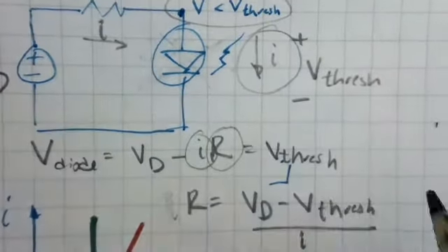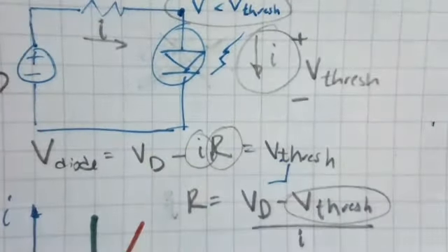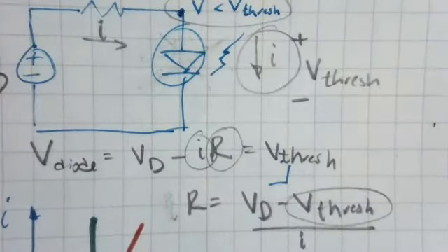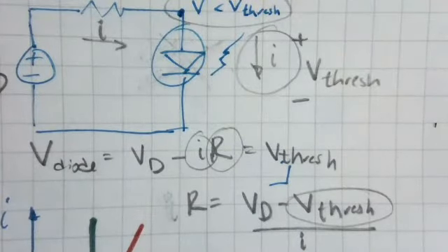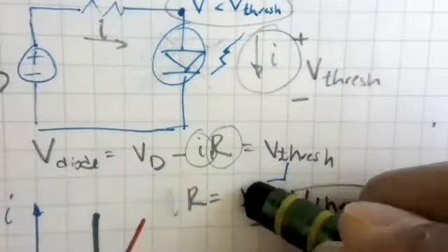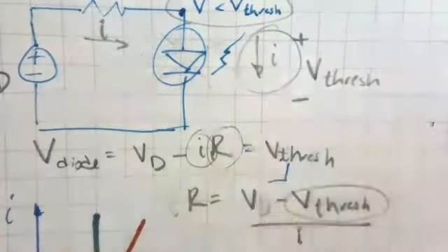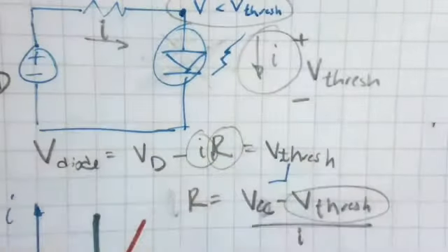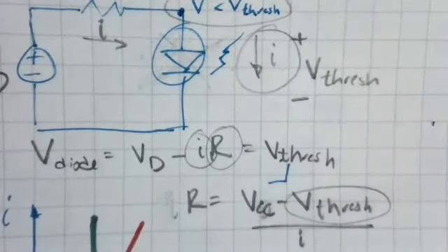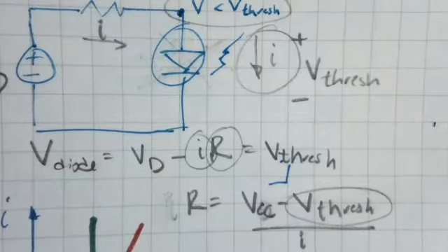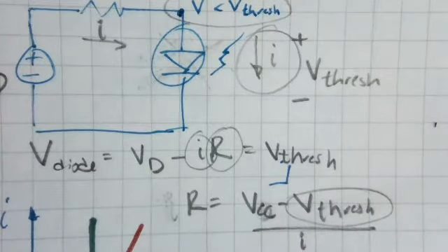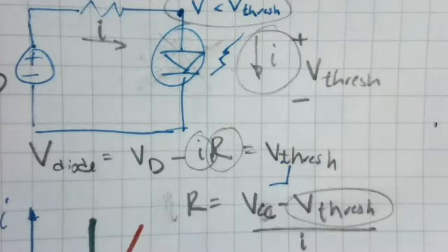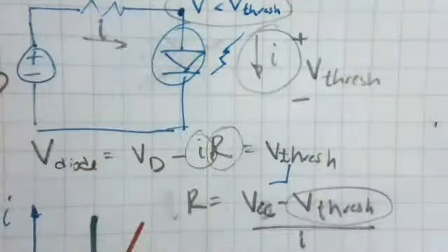Okay, I think many of you didn't include this factor, and that could be a fairly significant factor if the VCC for the MSP430 is 3 volts or 3.3 volts, and V thresh is 1.5 volts. Then that's almost 50% difference. Okay. So that's the first point about diodes.